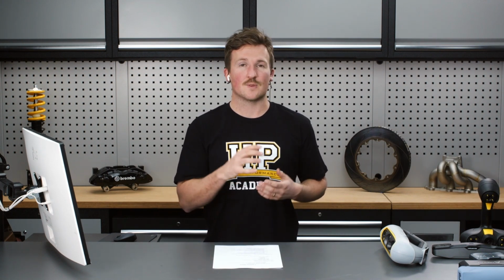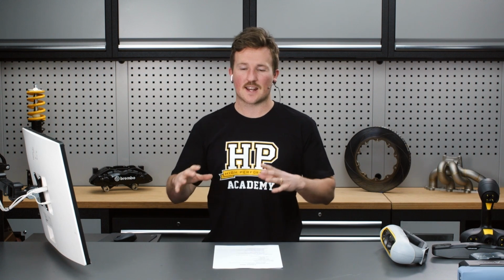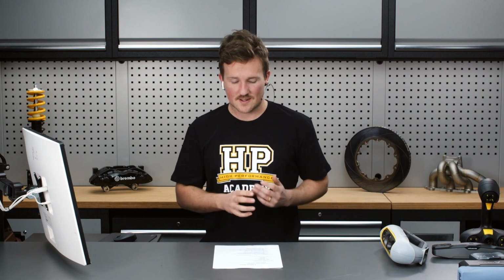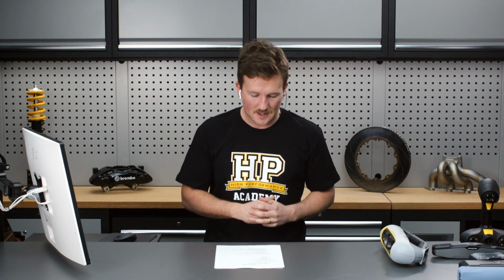So even though something might have the specs to say it's great, in the actual reality of using it, it might be really difficult tracking. That, I've found, has been the most frustrating thing in using 3D scanners: when you're trying to scan something and it keeps losing its tracking. That's where errors creep in, and it just takes a long time to scan something. But that is a difficult one to pick up off the specs of the scanner.